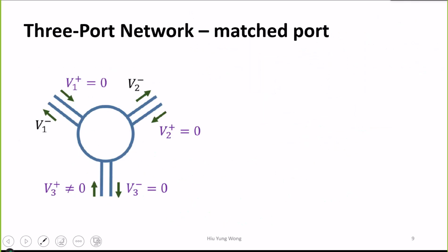Okay, now let's learn a little bit about another microwave electronics topic. We have been talking about two-port networks, right? The scattering matrix, the resonator, something goes in, something goes out. And the theory can be extended to many ports. It's also the scattering matrix. Here we show the three-port network. So if it is a three-port network, it has a matrix of 3 by 3. S equals S11, S12, S13, S21, S22, S23, S31, S32, S33.